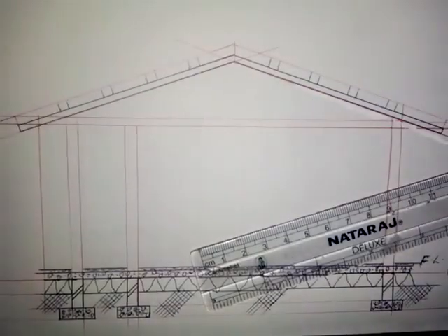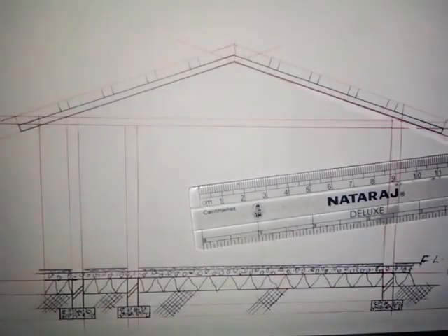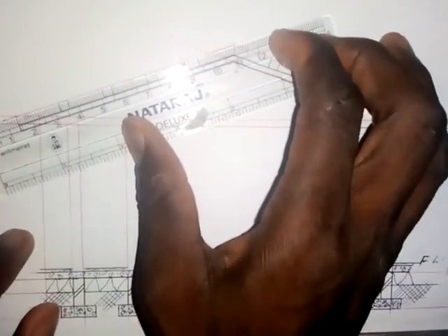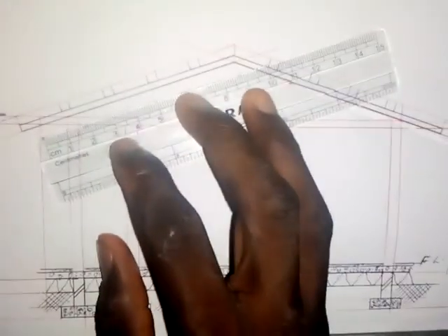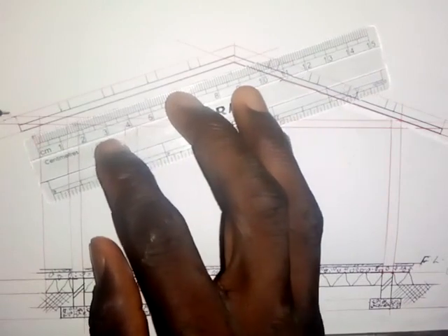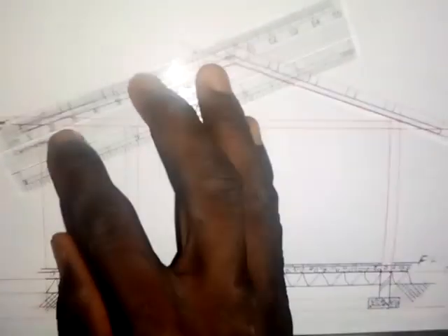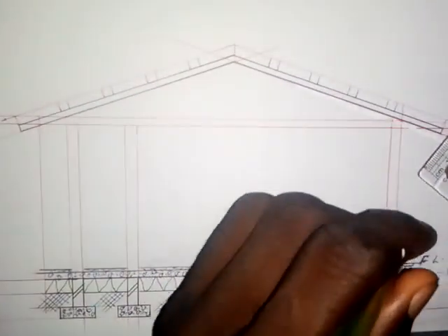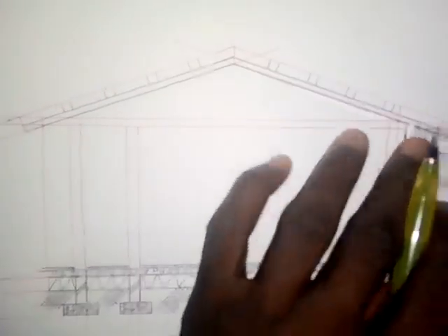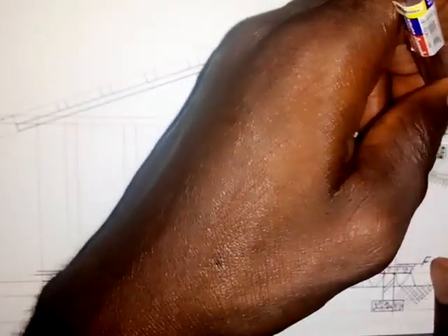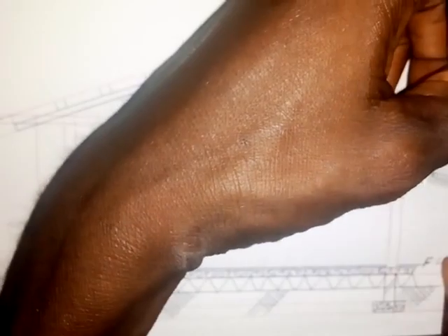All right, so we have this. It's on these purlins that the roofing sheets are laid. So from this end here, I take a measurement of 5 millimeters because the roofing sheet is going to be a little bit beyond this. And here I will also extend this a bit by 5 millimeters, to this side.